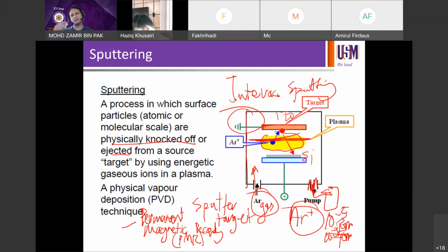Before that, all the magnetic layers use iron, Fe, cobalt, ruthenium, all those ferromagnetic materials. Okay. FeCo, Ru, Ti. You can check all the magnetic materials. There are magnetic components, right? So all are sputtered, right? So this is the same process. If you work at WD who make this, or previously Seagate or Fuji Electric that have a magnetic team. So I was in the Mag team last time. We call it the Mag team. Actually the magnetic sputtering. So this is the very process that we use in order to prepare your HDD.